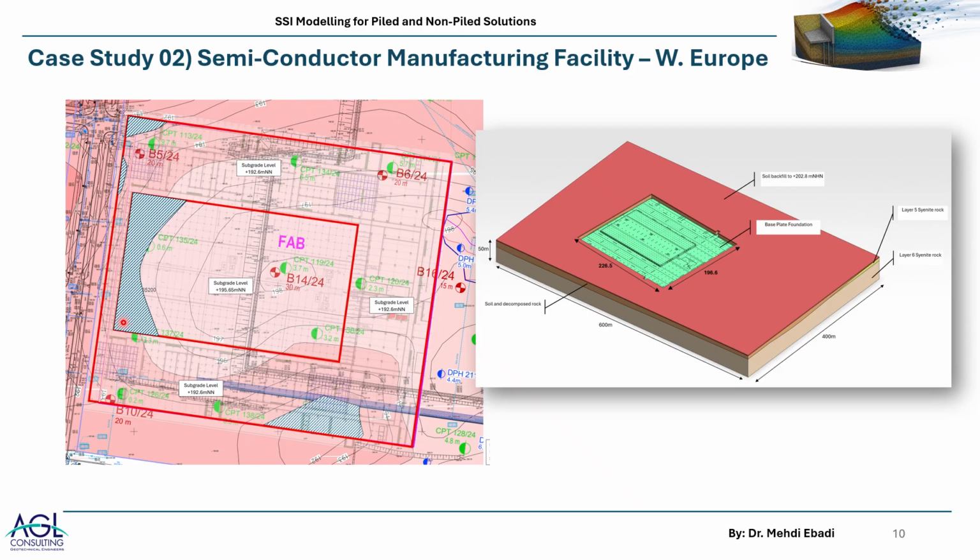So you may need to use items like extrude, like cut, like merge, those kind of things, like fuse in MIDAS to be able to replicate the same stratigraphy that you have obtained in your geotechnical analysis of the stratigraphy or have been provided to you.